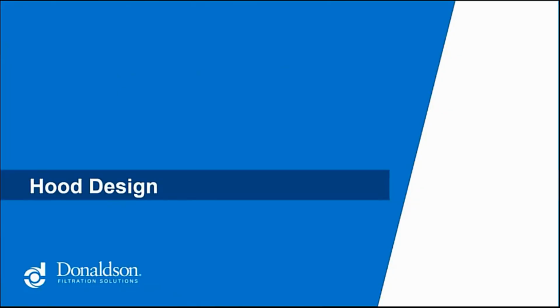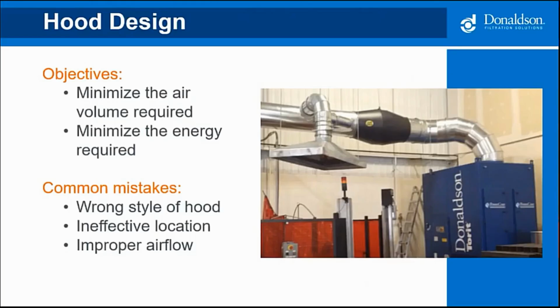So let's start with the hood. As I said, it is first. The objective here is to minimize air volume required and to minimize energy required. So let's expand a little bit on that. Air volume, you could design a hood that requires 1,000 CFM. You could then say, well, if 1,000 is good, I'm going to use 1,500. Well, we want to minimize it to what will work, but as we drive the air volume up, energy will go up as well. So going above and beyond is a good thing, but maybe not such a good thing.